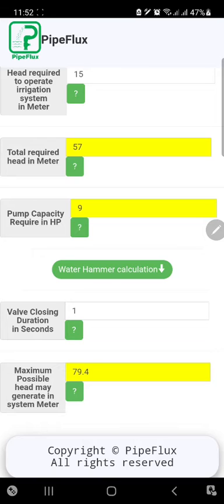Tripping of the pump may be due to power failure, any electrical failure in the panel of the pump, or any breakdowns. If the pump stops suddenly, the check valve on the delivery closes, and the moving water in the pipeline tends to come back with the gravitational force, even with more pressure. So it creates a pressure spike, which we are trying to calculate over here.